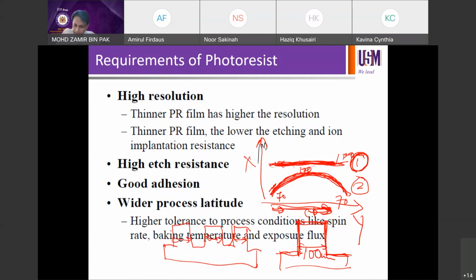So, yep. Does the CD only affect the photoresist? No. Photoresist is only one of the factors that could affect the CD. There are many more: scanner dose, focus, developer, hot plate, cool plate, robot arm positioning, resist expiry date, EBH, HMDS expiry date, many things. So when you have, for example, one CD drift issue, you cannot really pinpoint the top 2-3 factors. It really depends on the nature of the problem.